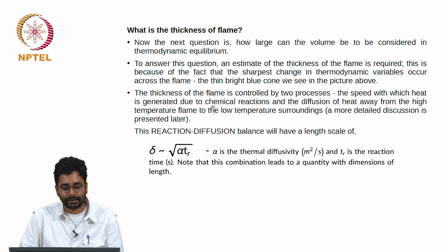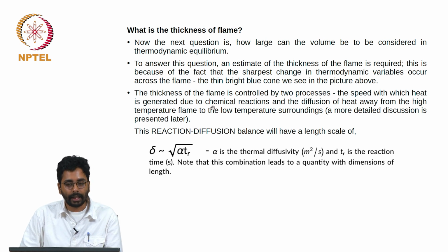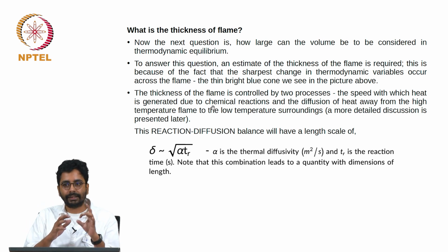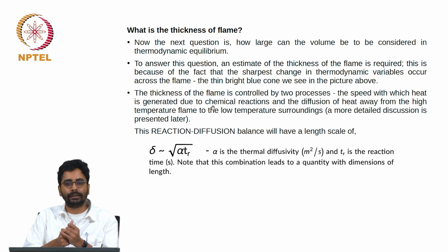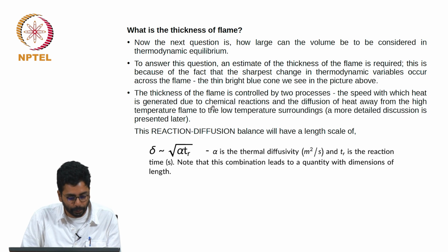To answer this question, we need an estimate of the flame thickness. This is because, I am repeating this point, the sharpest changes in thermodynamic variables occur across the flame, the thin bright blue cone we saw in the pictures above. This is something important. This is something that we will use many times in this course.